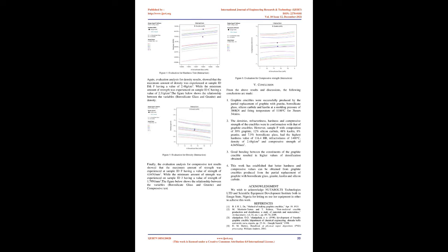For results and discussion, an introductory study on graphite crucible composite, GCC, formulation was done by investigating the components that made up the crucible material. 4 excipients were chosen for the GCC formulation based on their function. 3 of them and graphite were used as variables in response surface methodology, RSM, as they may have an effect on the responses. The ranges of variables were also studied by using RSM in Design Expert software.